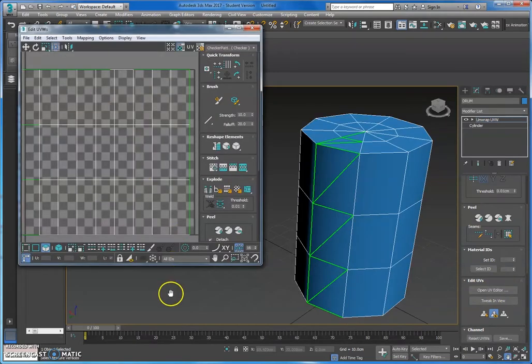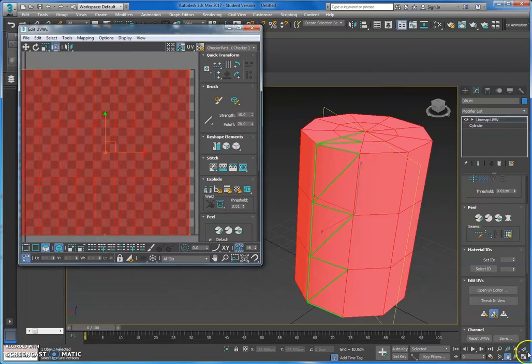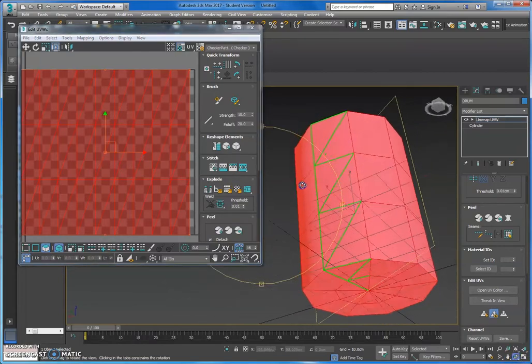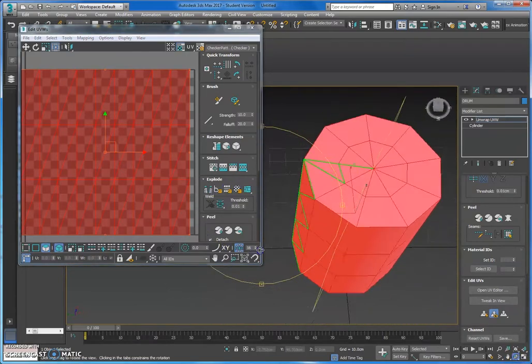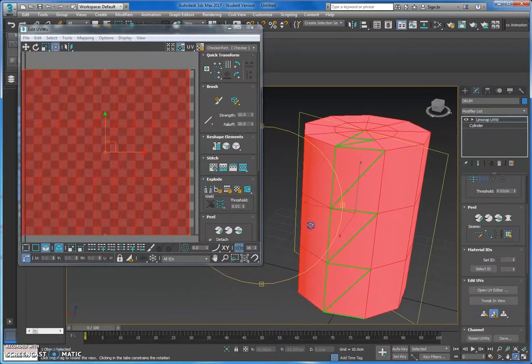To select all of the texture coordinates, make sure the Select by Element UV toggle is selected. Click on any of the texture coordinate elements in the Edit UVW editor window. It should turn red, and the mesh also turns red in the perspective window. With the texture coordinates, we are going to alter how they are projected so we can create a template to